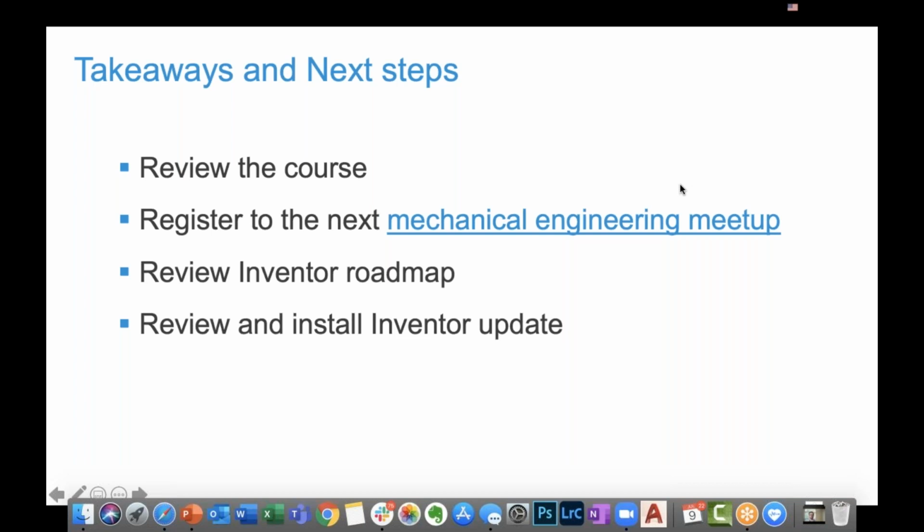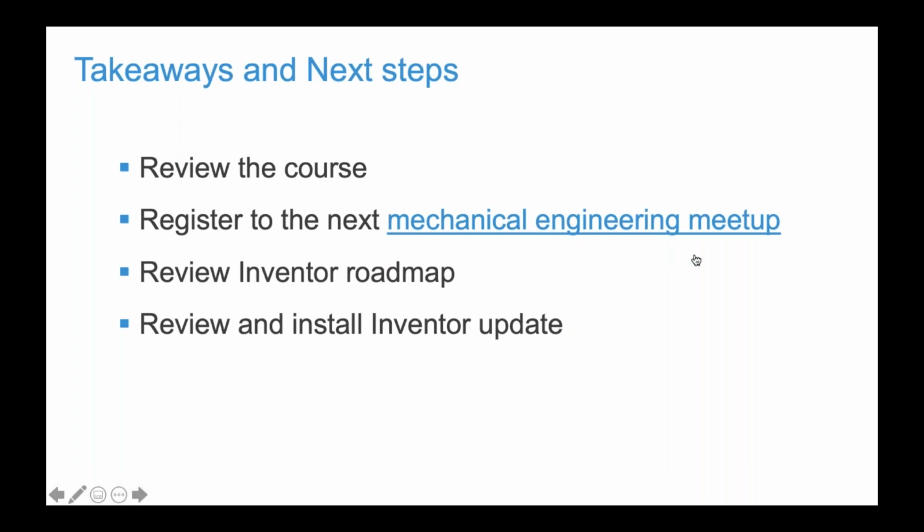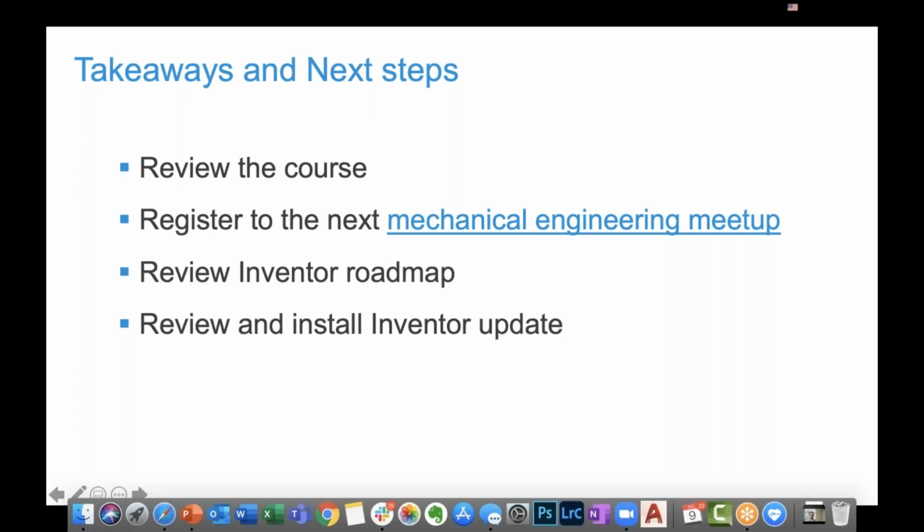Basically, no. I hate to shut this down, but 3ds Max is primarily a mesh-based editing software, whereas Inventor uses solid bodies, so there's really no easy way to bring it in. To a certain degree, with Fusion, because there is a little more mesh-based editing in there, that's a possibility. But I've actually received this question for years off and on, and to be honest, it's not an area I would consider looking into. Unfortunately, that's just the way that it works.